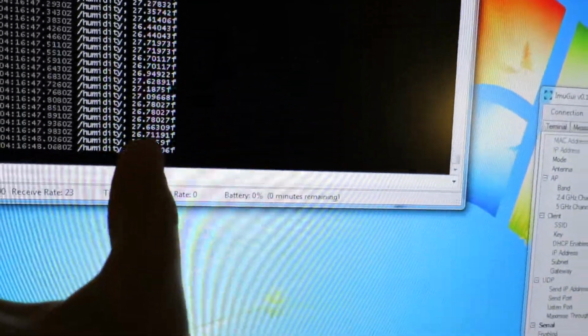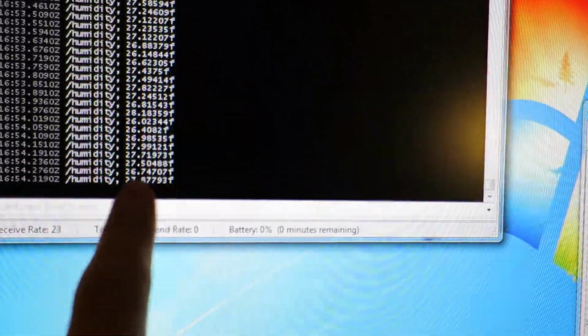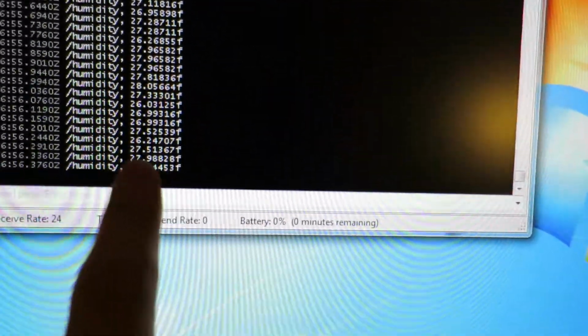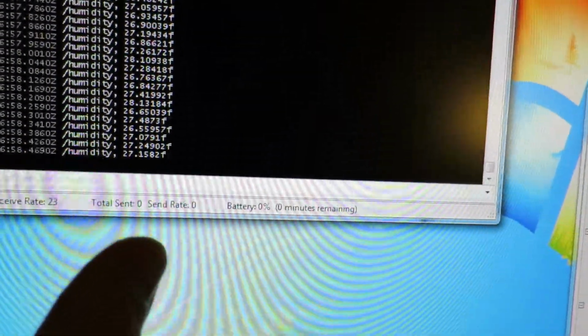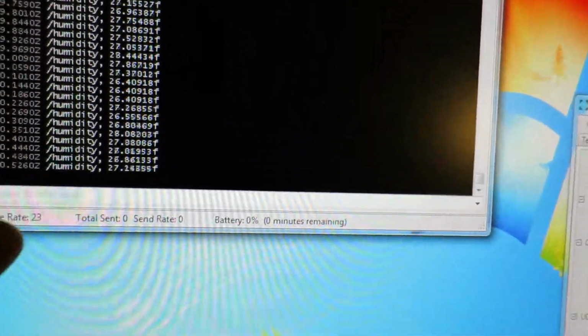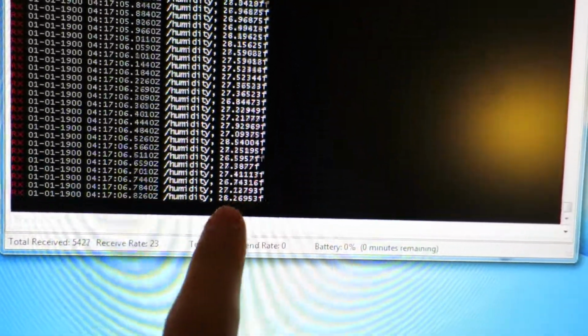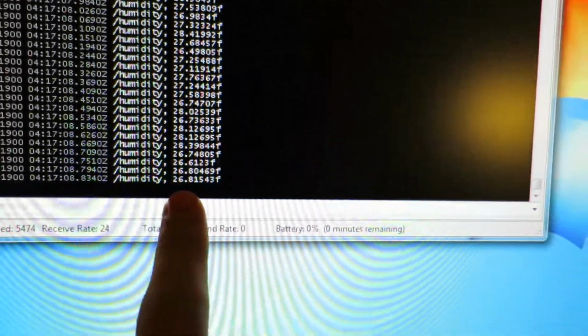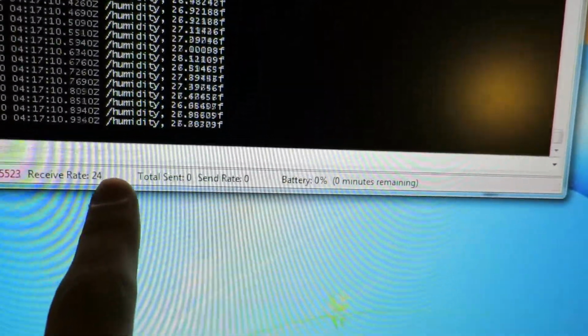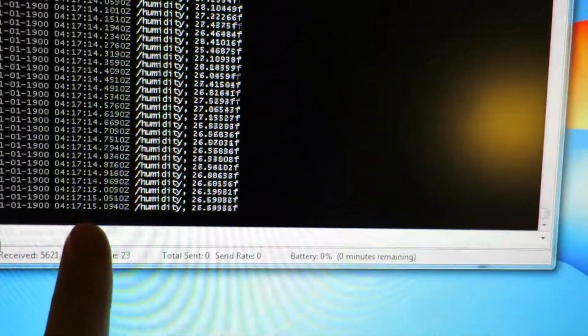So this is pretty inefficient encoding using an OSC bundle and just OSC in general. If all it needs to be transmitted is one float, 4 bytes, and it's 44 bytes long, you can easily get 10 times the throughput with more efficient encoding. So in this specific example, if all we want to do is transmit that number, we could get 240 messages per second, around that, with more efficient encoding.